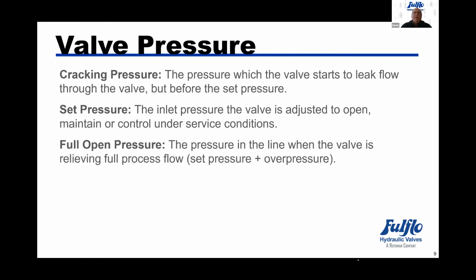It's also based on the viscosity of the fluid. Water is going to leak a lot sooner than oil will because it's going to vent through the valve and on out to the discharge, where a higher viscous fluid will not do that because it can't leak through the valve and back out. So that's cracking pressure.